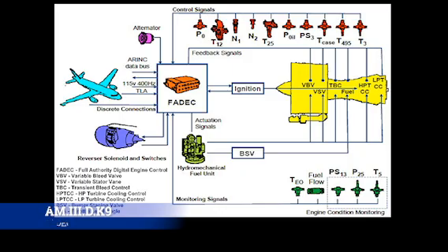It provides diagnostic data via ECAMs and helps monitor all the problems that happen with the engine, so you can come with a maintenance laptop and just download it and then start troubleshooting. Now, this reduces the pilot workload, and honestly, it reduces the maintainer workload as well, because you don't have to run and guess. It improves safety by preventing operation outside of certified limits, enhances precision engine control, it improves efficiency, and it also reduces wear because you don't have any of the weird human factors that factor into it.